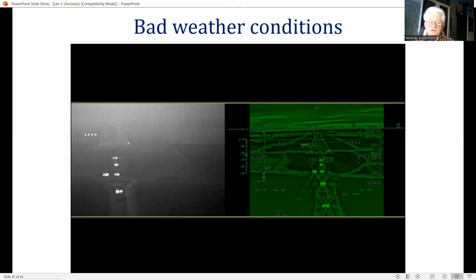They were routinely able to fly to Category 3A minima, from 50 feet decision height and 70 feet runway visual range, using the HUD display of the radar-generated runway image and the overlaid primary flight symbology as their sole means to conduct the published approach.